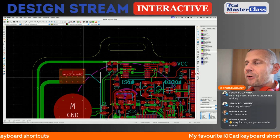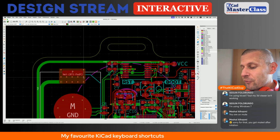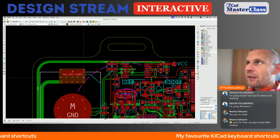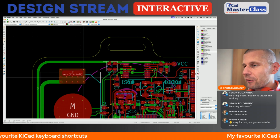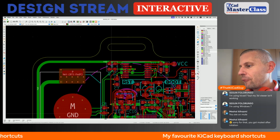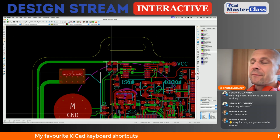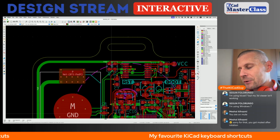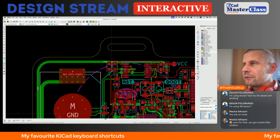My routing grid is 1 mil, but when I'm drawing polygons, I sometimes use the 5 mil grid. So holding Shift and pressing N, this is 2 mil and 5 mil. So twice N, I'm on 5 mil grid. So very, very fast change of the grid. But you have to always check the grid when you continue routing or drawing edges, because KiCad remembers the last chosen grid.